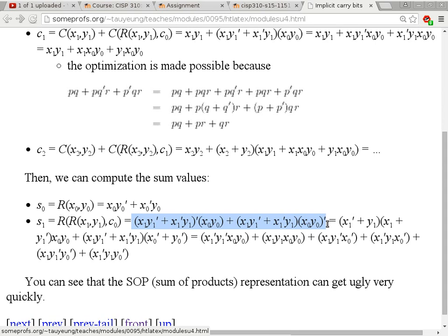Yep. If the 64-bit processor is adding 2 3-bit numbers and has a bunch of leading zeros, will it add the leading zeros or carry the zero? Okay. The full adder does not really care, because there is no special hardware for special numbers. So when we talk about a 64-bit by 64-bit adder, it is designed to handle general purpose 64-bit by 64-bit addition. Okay.